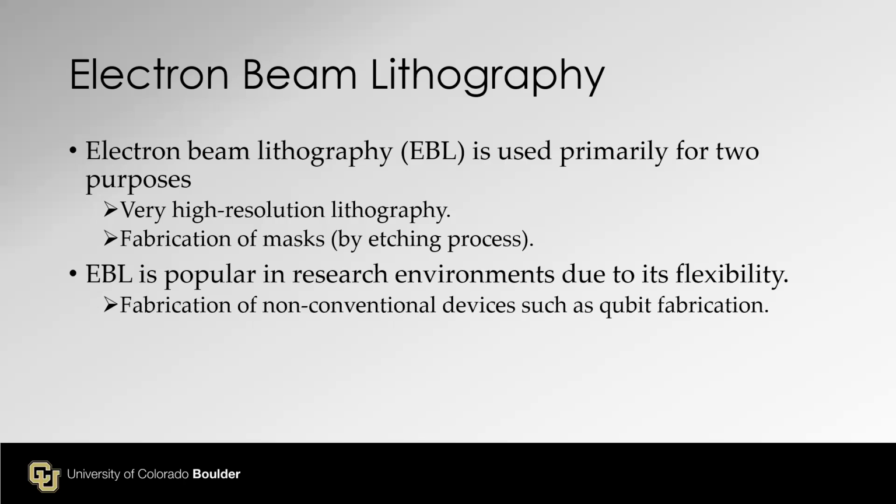So we don't have an EUV system or deep UV system. Yes, in theory, we can use the electron beam direct writer to prepare masks, but no one can use it that way in a clean room. Intel, I think, has an E-beam writer and is making masks for EUV systems, but not for us.